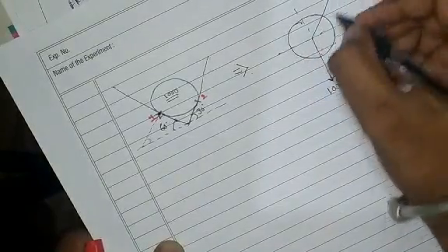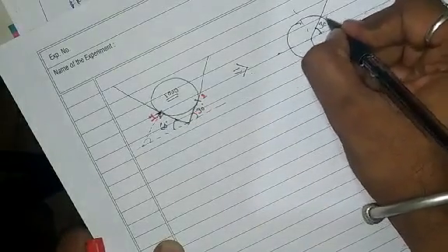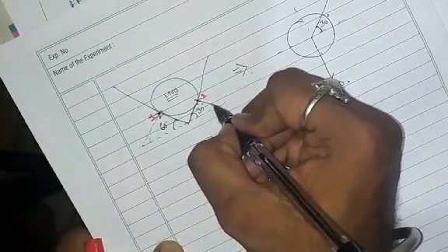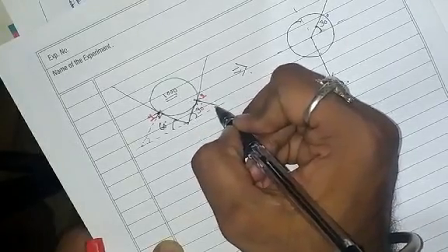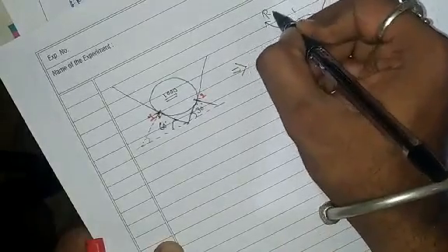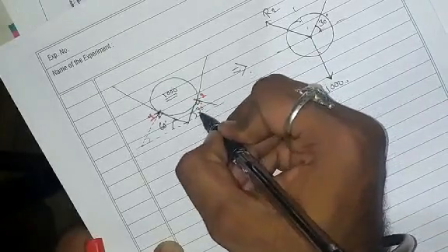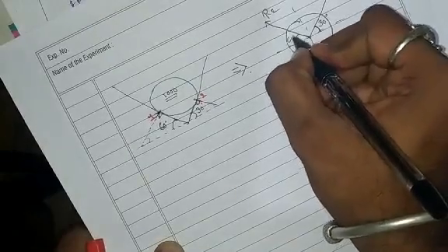So this is the R1 force, angle is 30 degrees. Similarly, if you consider R2, this is R2. Now in which quadrant is R2 acting? In the second quadrant. Now this is 90 here, this is 30, that means here the angle is 90 plus 30 minus 180, that is 60. Yes, this is 60.